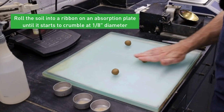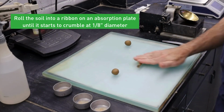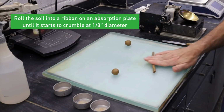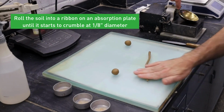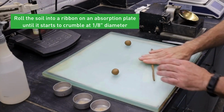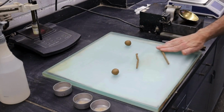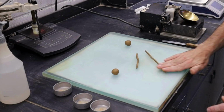Basically, I just roll these out until you cannot, once it starts to crumble. Until it crumbles. If it crumbles when it's thicker than that pin, thicker than 1/8 inch, then we know it's too dry. And if it starts to crumble when it's even thinner, we know it's too wet, because moisture lubricates things and helps to draw out that ribbon.